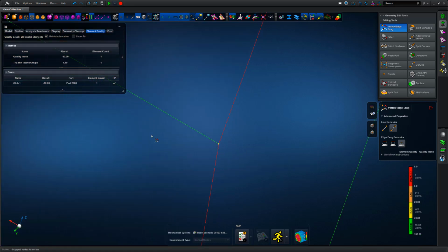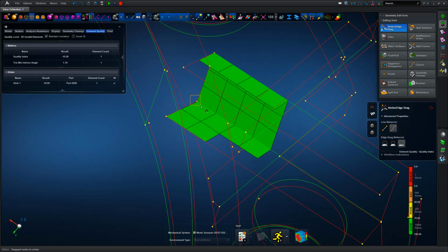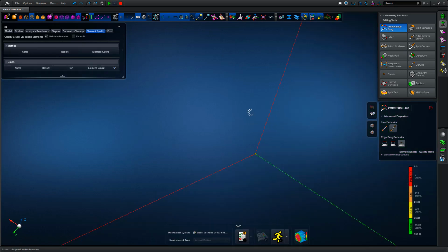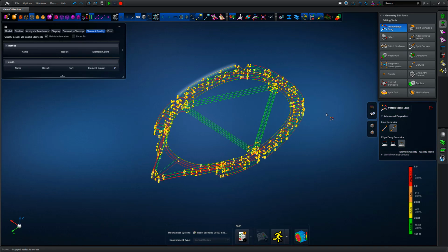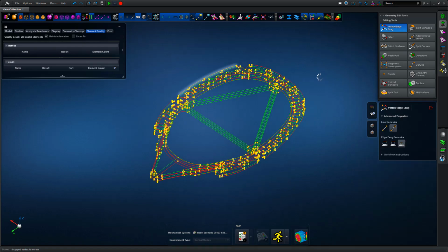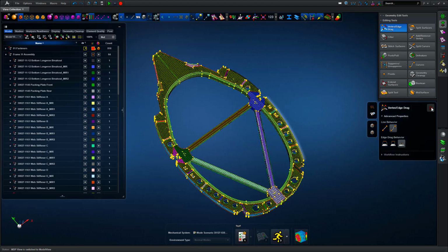We could perhaps tailor the mid-surfacing operation to work in a slightly cleaner manner, both from a defeaturing and a resultant mid-surface definition perspective. But we just hit this model with quite a broad set of parameters to show the overall technique that we would use for that definition.